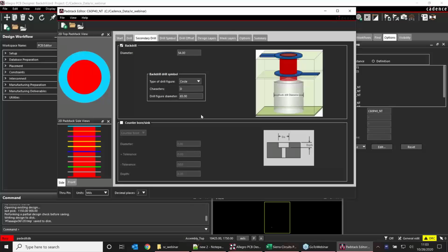Another thing is that prepreg thickness, or any dielectric thickness, also depends upon the application. If you are using a very high voltage board, let us say boards in which the voltage across 2 layers can be as much as 1000 volts, in that case it will be governed more by the electrical strength of the dielectric layer. So that puts another constraint on it.